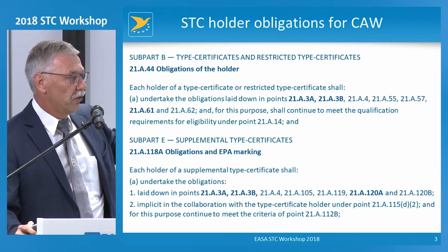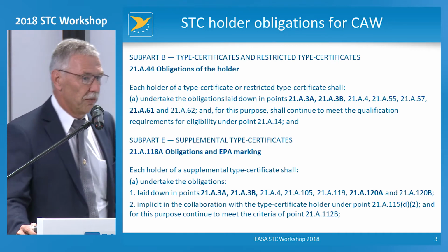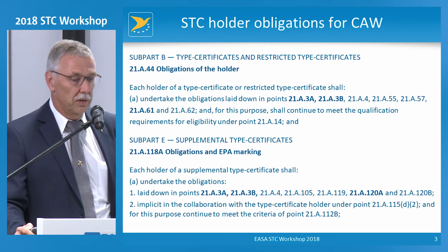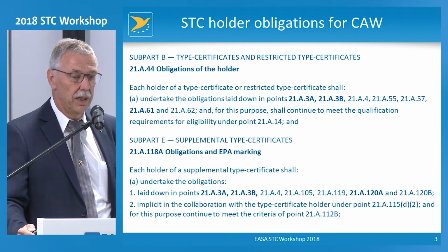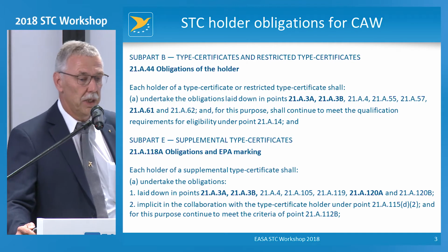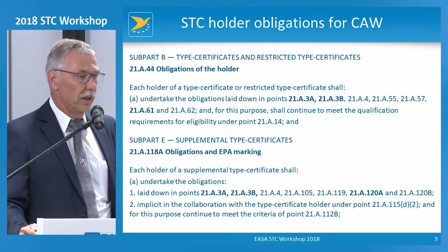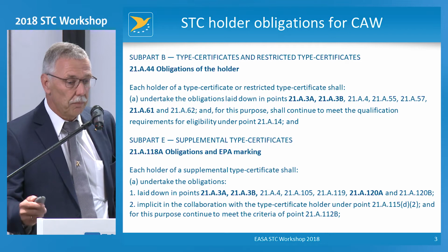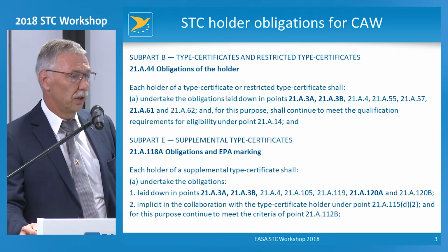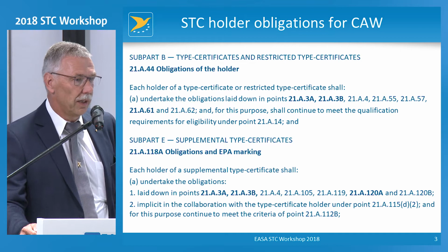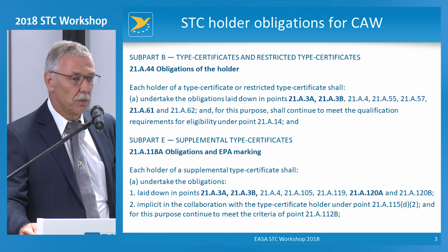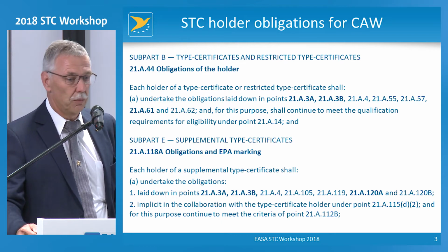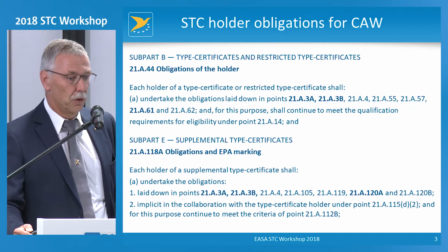On this slide, I have just put together the obligations of the TC holder and the STC holder with respect to continued airworthiness. It's 21A3A and 21A3B, and you see on both sides the obligations are the same, and therefore you must know that you have a system to collect occurrence reports and to deal with them, and also to inform EASA about them so that we can work together and fix the problems if they arise.